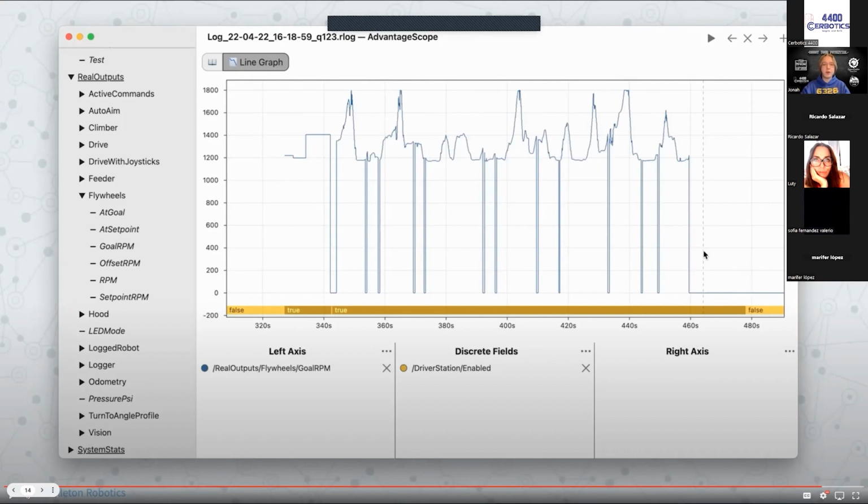Unfortunately, it looks like we forgot to log the distance to the target. Now, the measured distance is based on the robot's odometry, which in turn used vision data, wheel encoders, gyro angle, etc. as inputs. And because all of those inputs are logged, we can extract the measured distance to the target using the log. Except there's a problem.